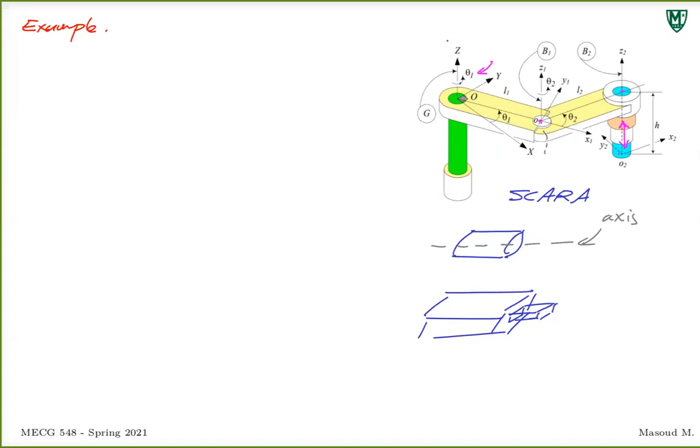If someone tells you we rotate plus 20 degrees, it means going in the theta 1 direction. If they tell you we rotate minus 40 degrees, it means you are rotating 40 degrees in the opposite direction, like in this direction. That's what is important: the sense of positive and negative when it comes to a revolute joint.